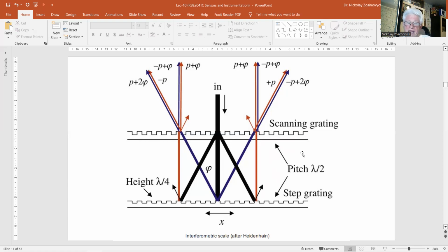The design is made in such a way that the diffracted beams interfere when entering back to the scanning scale. For each of the 3 directions, the phase difference of the interfering waves is equal to pi. Each time the wavefront passes the scanning grating, it experiences an additional constant phase shift. By design, this phase shift is pi for the 0th order diffracted waves and 0 for the other waves.